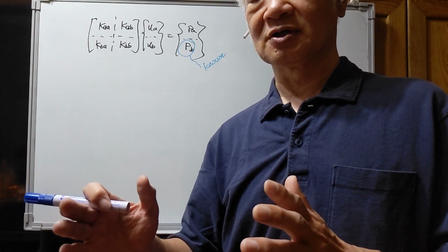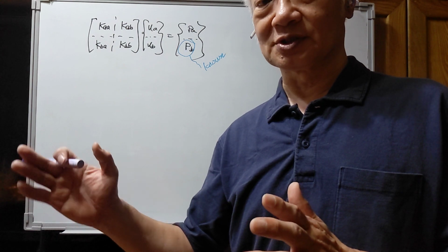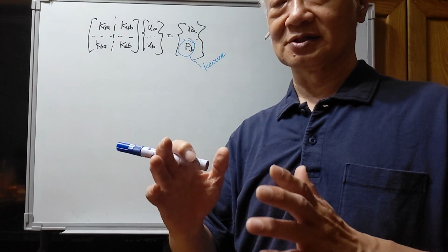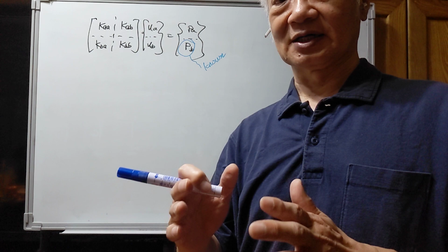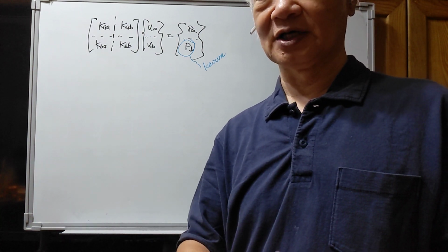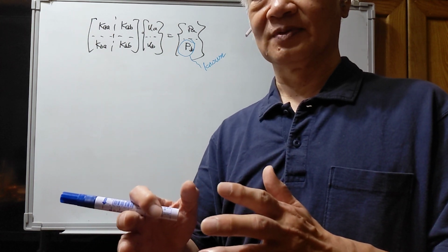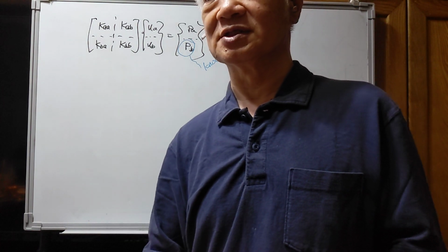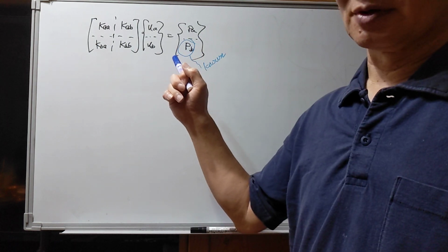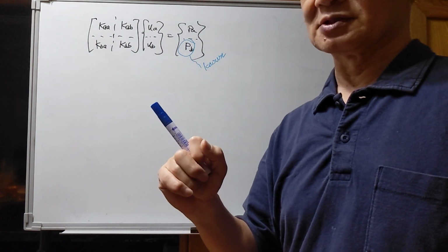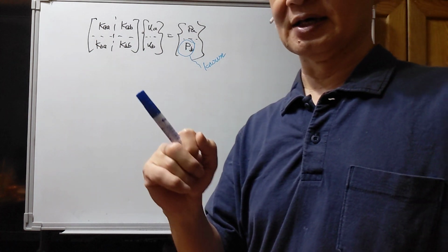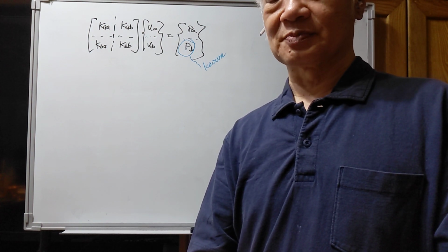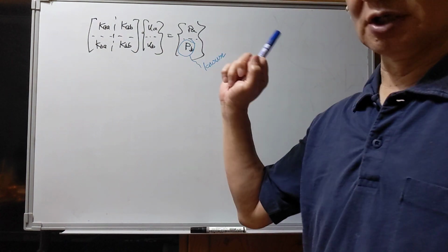But that's the procedure in the post-processor. But right now we are still in the processor. The processor is where we are trying to calculate the element stiffness matrix. We need to assemble them into the global stiffness matrix, modify the boundary conditions, then we can solve the basic unknowns. But right now we don't know the elements. Okay. Only for some special case. If you have a pin end at the member end, it is a special condition. For this special condition, we know the bending moment is equal to 0.